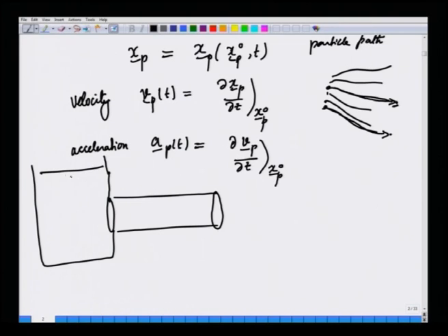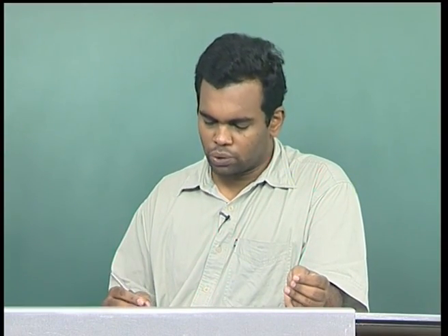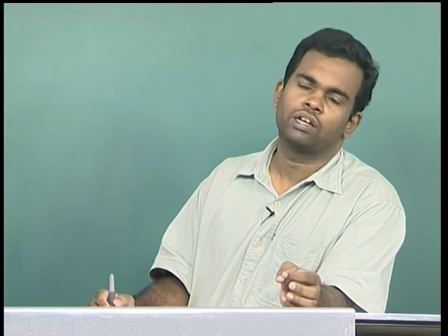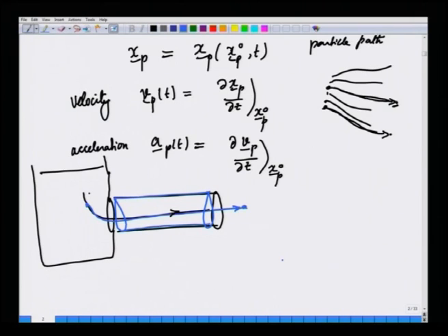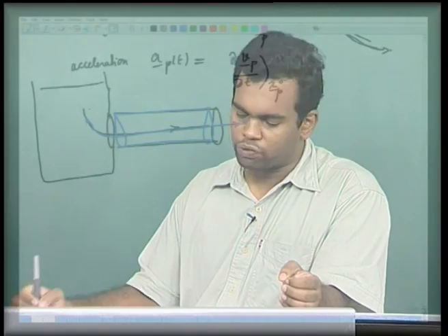Okay. So, if you are interested in the pressure drop across the pipe that is required to pump a specific flow rate, then you are not truly worried about the identity of the fluid particles that are entering and leaving, because all you are interested in is the force that is being experienced by this pipe, what the drag force is, and consequently what the pressure drop is. So, the Lagrangian description, wherein we follow the same particle as a function of time, is really not very useful, especially when you are considering fluid flow problems.